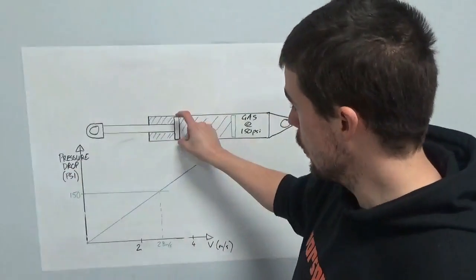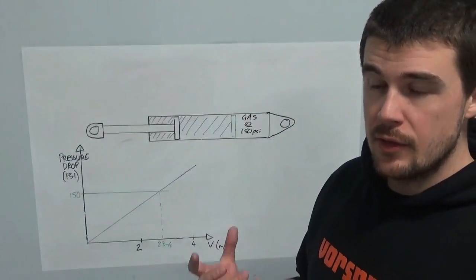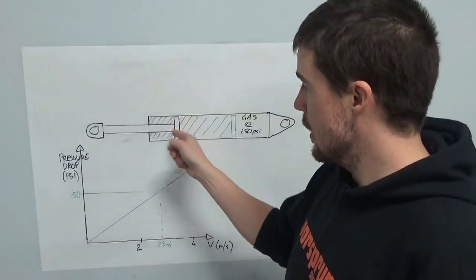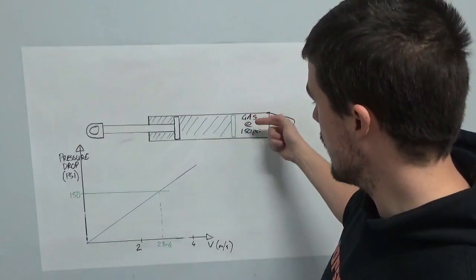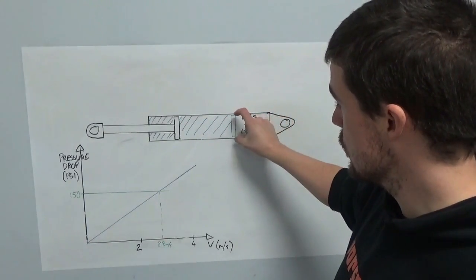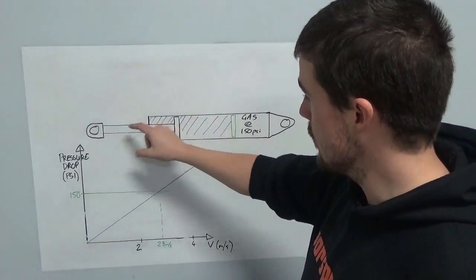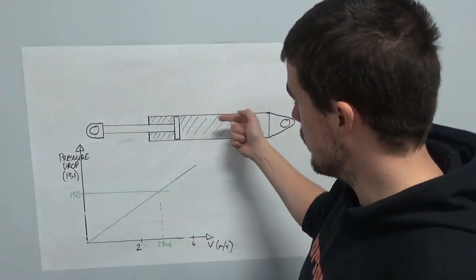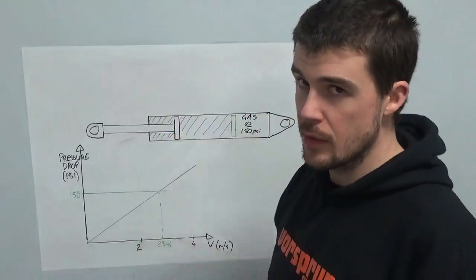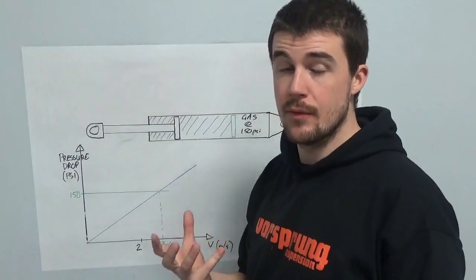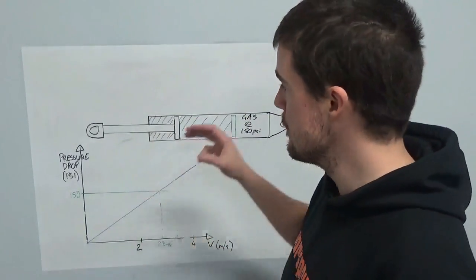Pressure drop over this piston here, this one in the middle, is effectively what gives us a damping force in a monotube system like this. So here we have a gas charge pushing an IFP. The IFP pressurizes the oil, and basically that means that when this compresses, it's that pressure of the oil that forces the oil through the valve, through the shim stack, through the low-speed bleed, whatever it may be.